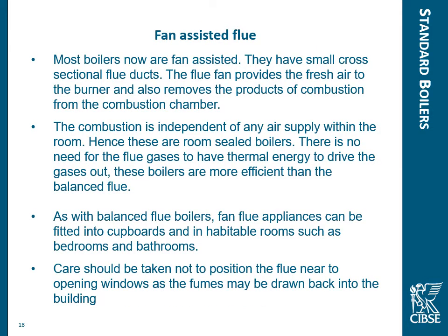So most boilers now are fan assisted, with small cross section areas. The flue provides the fresh air and the burner removes the combustion gases through the centre of the flue there. As with balanced flue boilers, they can be fitted into cupboards and habitable rooms. And again, care should be taken where the flue discharges.